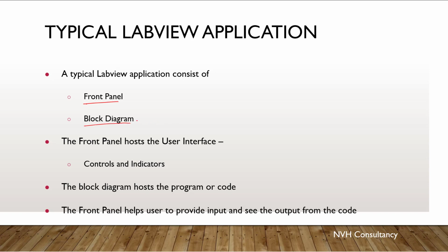The block diagram is like the brain of your LabVIEW, and the front panel is your screen. This is what you will see outside, and that way the whole application is divided. The front panel will host the user interface. It will have all the controls and indicators.